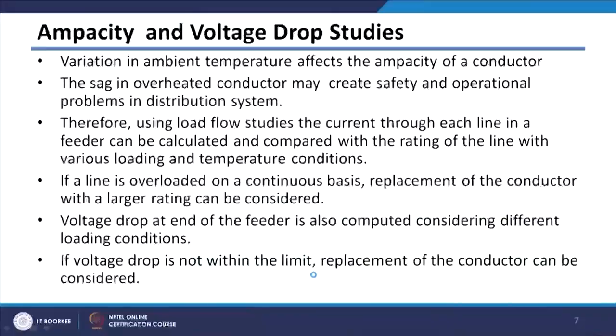Then third is ampacity and voltage drop studies. Ampacity is nothing but the current carrying capacity of your conductor. However, this current carrying capacity depends on ambient temperature. Whenever temperature increases, the resistance of the conductor increases, and because of that resistance, your ampacity decreases.